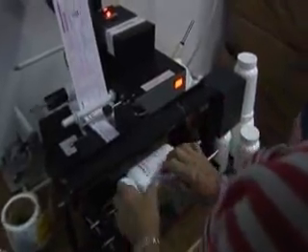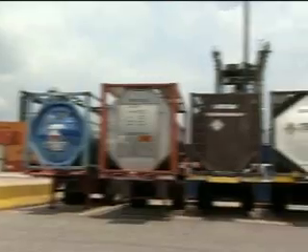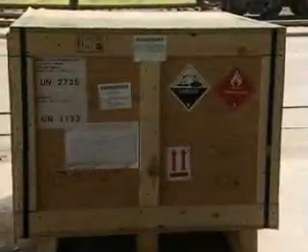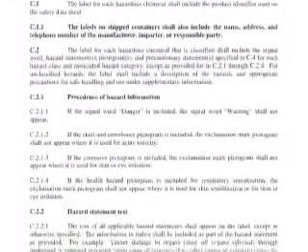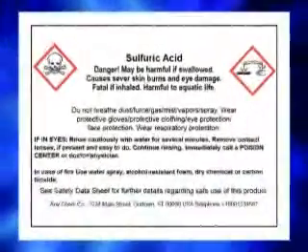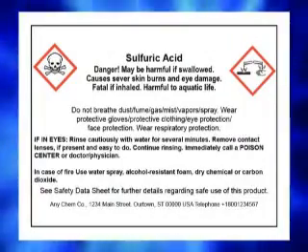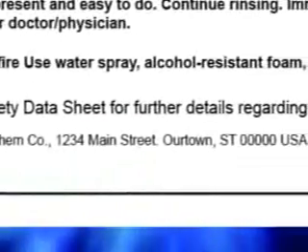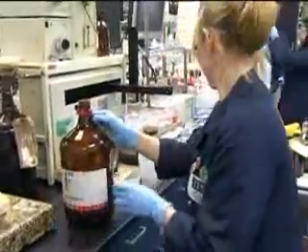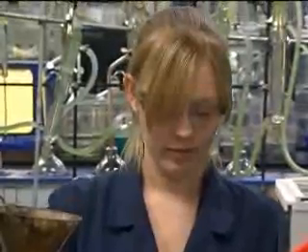Labels are affixed to, printed on, or attached to the container of a hazardous chemical or the outside packaging. Chemical manufacturers, importers, and distributors are responsible for labeling, tagging, or marking each container. OSHA mandated Appendix C of the HCS to guide them on the correct information to place on chemical labels. The label must be prominently displayed in English on each container and must include the name, address, and telephone number of the manufacturer, importer, or other responsible party. Employees should know how to read chemical labels and understand the information presented before dealing with hazardous chemicals.